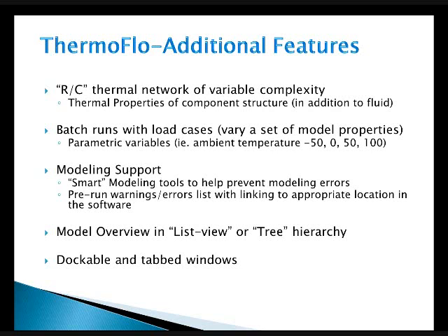And then there's several different modeling support things. One is the smart modeling tools to prevent any kind of modeling errors, where it's going to give warnings and errors if it does see anything that may be a problem, and you can adjust these for your industry so that they're not set for, perhaps, a 1 meter diameter pipe is reasonable to some people, but is ridiculous to others. So you can change what those are to prevent any kind of unit issues.